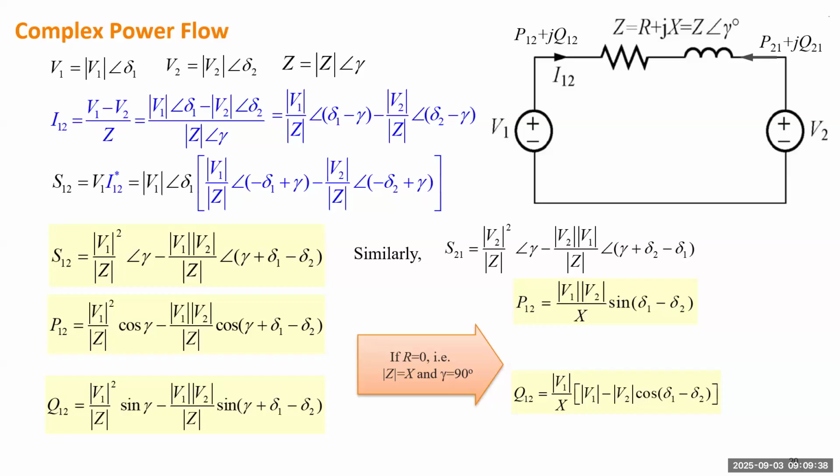Okay, last week we used this circuit to develop the accurate formula to calculate complex power sent from one end to the other end through a transmission line. So this circuit is very general, with impedance having both resistance and reactance, and two sides will have two voltages. We don't worry about whether they're load or maybe a source, but we know the voltage phasors V1 and V2. So they may have different magnitude and different angles. V1 can be leading V2, or V1 can be lagging V2.